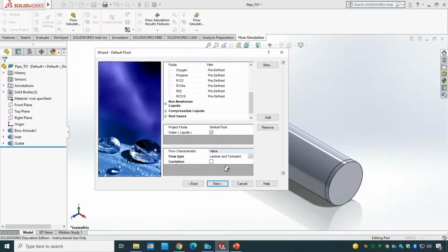And then I have to talk about the flow types, whether it's a laminar flow, which basically is a nice and steady flow, or whether it's a turbulent one, where the velocity goes up, the Reynolds number gets high, and then you have the vortex, the turbulent vortices. This is also how we apply the Navier-Stokes equation to it.